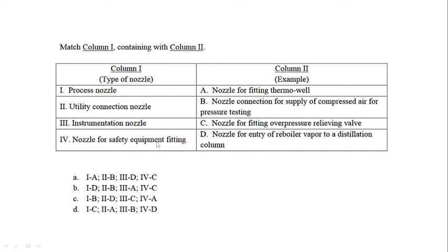The stability, accuracy, and repeatability are higher than a thermocouple, and it works on the principle that there will be a platinum wire which, when heated up, will expand linearly. So there will be a resistor also to measure that. When the temperature increases, the resistance will be higher.